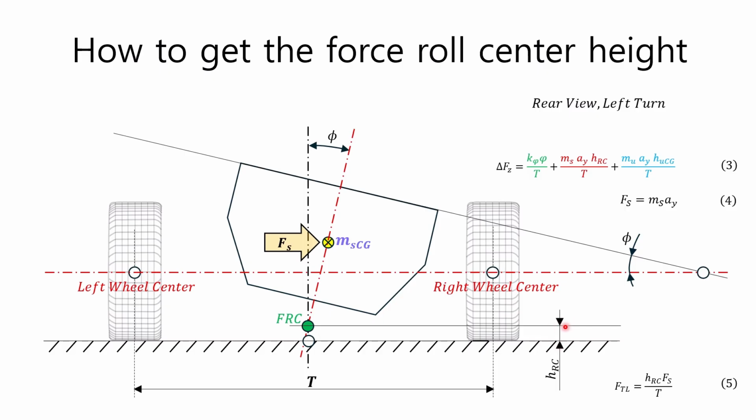The amount of load transferred through the link can be found by analyzing the magnitude of the force acting on the suspension link using a computer, or by measuring the force acting on the link using a sensor attached to the link. Since it is very difficult to exactly reproduce the road driving condition of a vehicle subjected to lateral acceleration in a test laboratory, the most reliable method is to measure the force caused in the link under various lateral accelerations while actually driving on the road.